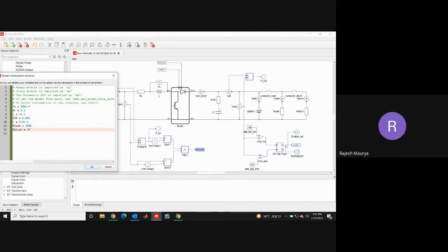If you take the truth table logic for the SR flip-flop, you will find that whenever it goes above 52, we'll get the signal as 0 from this Q. That means the boost converter would be disabled. Here we are giving the enable signal, so if it gives 0 over here, it will be disabled and will not charge the battery. At that point the battery will supply this R load and R discharge resistors. But when it drops below 49, it will enable it and charge the battery. So the boost converter is like an open circuit when disabled.